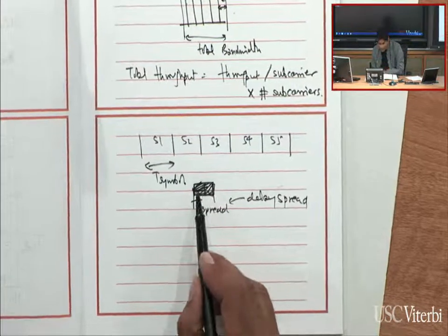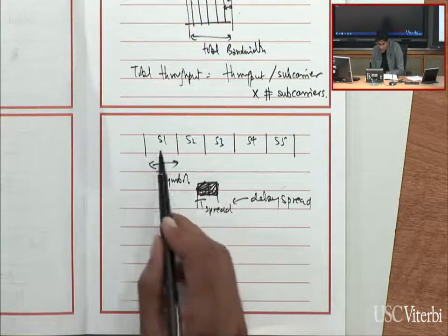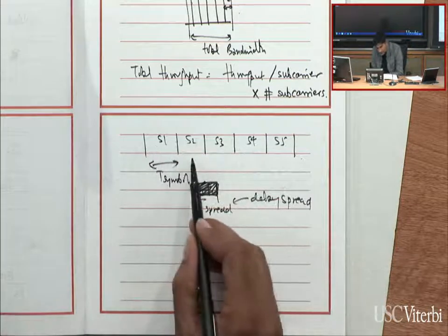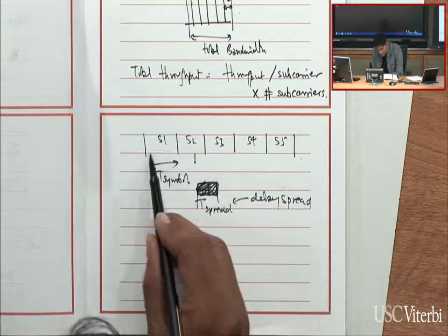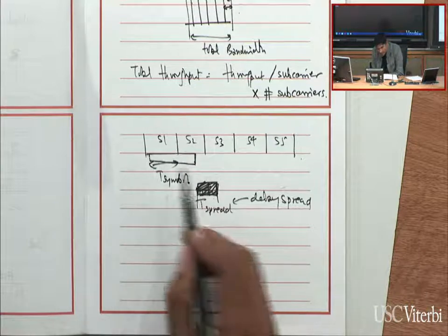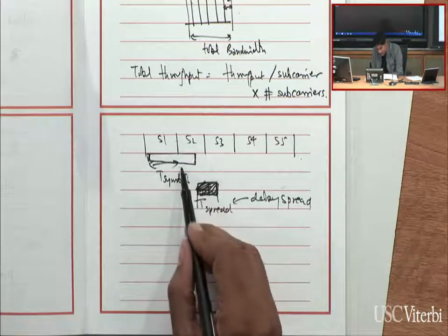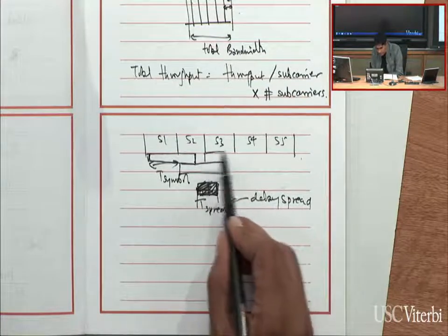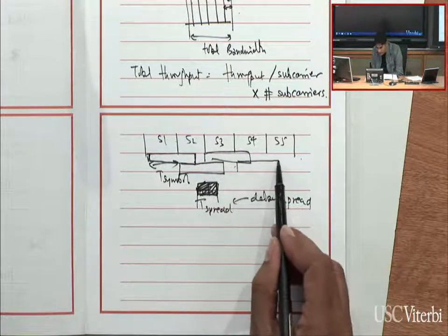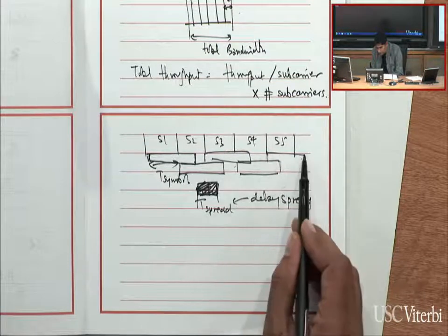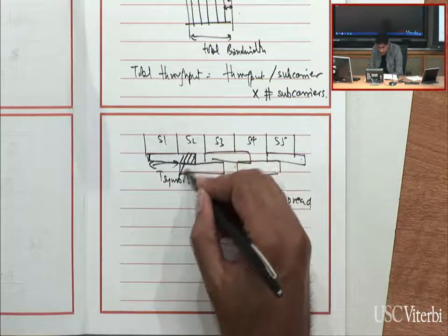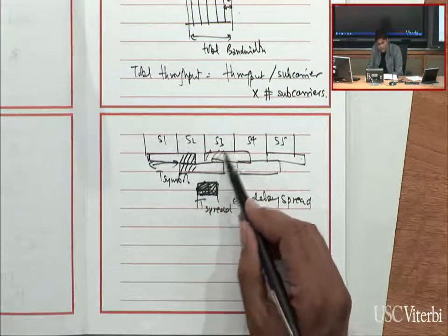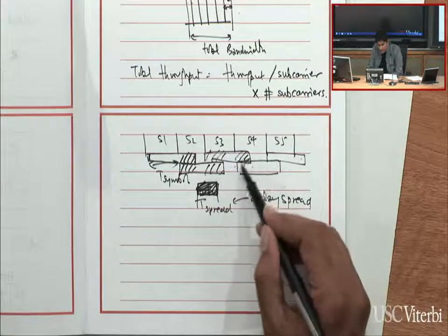When I get these additional versions of that symbol, some of them are going to smear into the next symbol. So what I receive looks like I got this, plus I got something where the first symbol is smearing into the next symbol. This symbol will arrive but smeared into the next symbol. The third symbol will be smeared into this symbol, and so on. Because of this period of time where the symbols are interfering with each other, I'll have a tough time decoding each of these symbols. It's as if I'm interfering with myself.